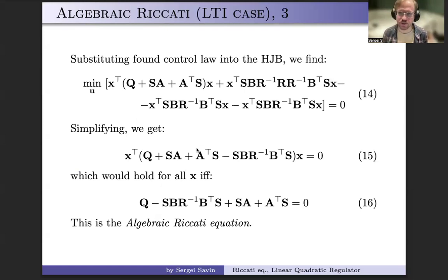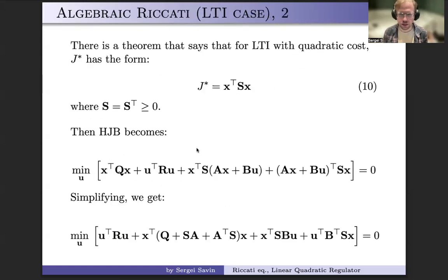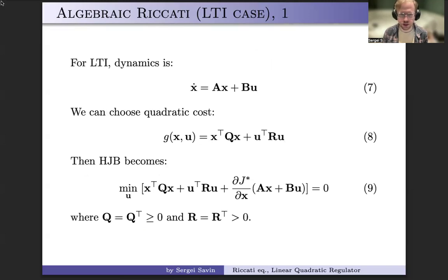Well, there is actually a reason. First of all, here we assumed that A and B are constants. What you would find if you are going to do research is that often it is a bad assumption. Often it is better to assume that they are changing with time. For example, when you follow a trajectory, you can assume that your A and B matrices are changing on this trajectory. That has to do with linearization techniques.